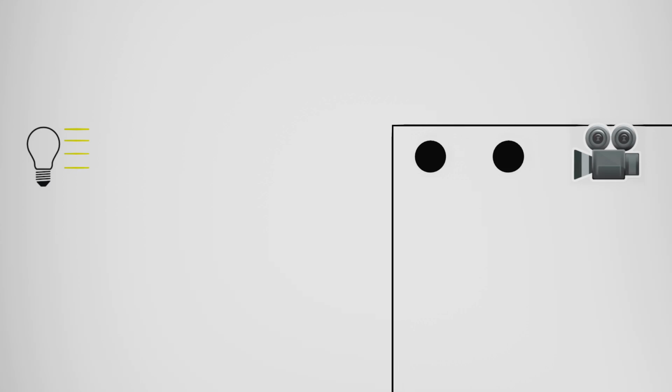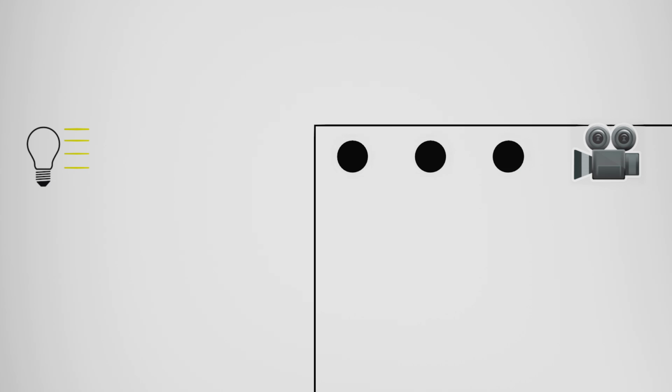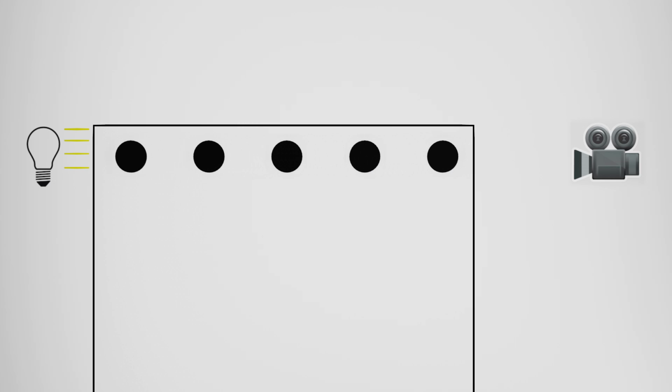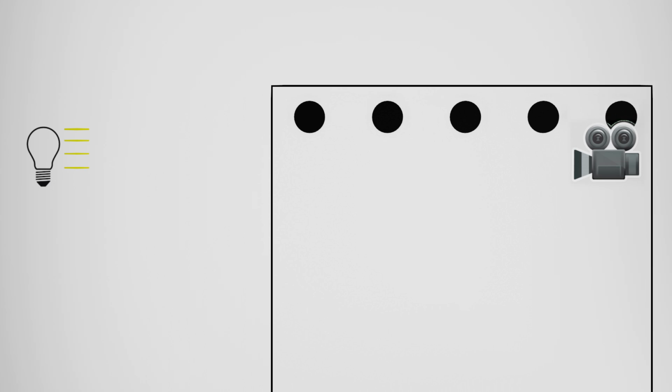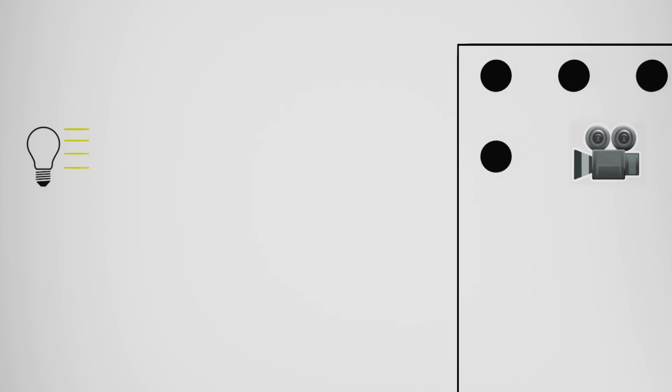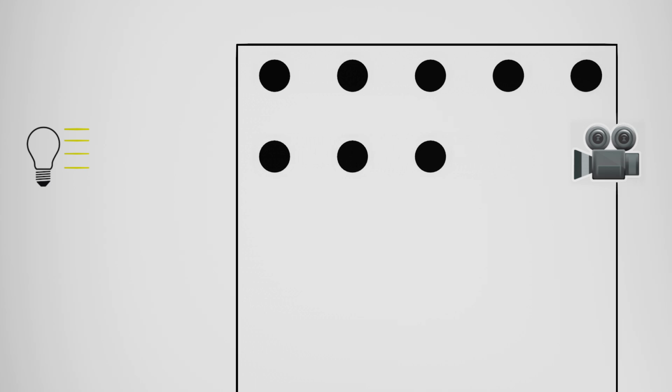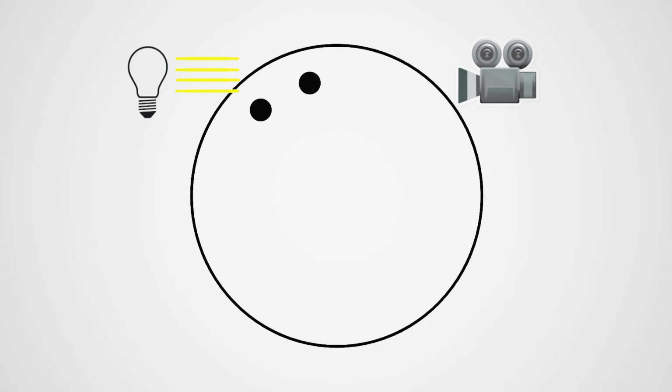For each test, multiple craters have to be shot at different locations on the sample. So, the sample has to be moved relative to the laser. Two ways to move the sample are moving the entire channel and mounting the camera and lead fixed relative to the laser, or rotating the sample and mounting the camera and lead to the channel. The latter option is preferred as the camera and lead cannot accidentally clash with the channel during the homing procedure of the X and Y stage which the channel is mounted to.